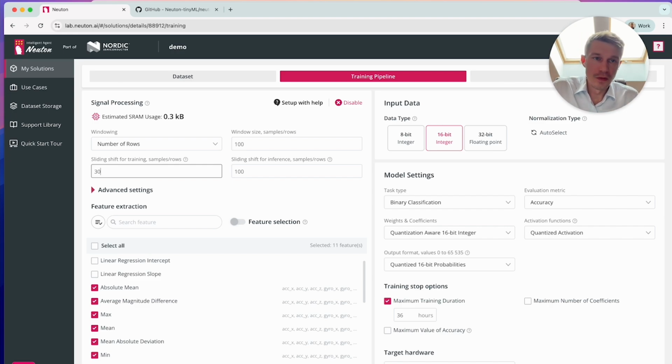And we also do have a repository with code that does this pre-processing for you. It's a Python script that basically you tell it what is the window size, you use your whole data set with all the examples of all the gestures just before you upload it to the platform. And the only inputs in there are the window size, let's say 100, and you flag those classes which are discrete in nature.